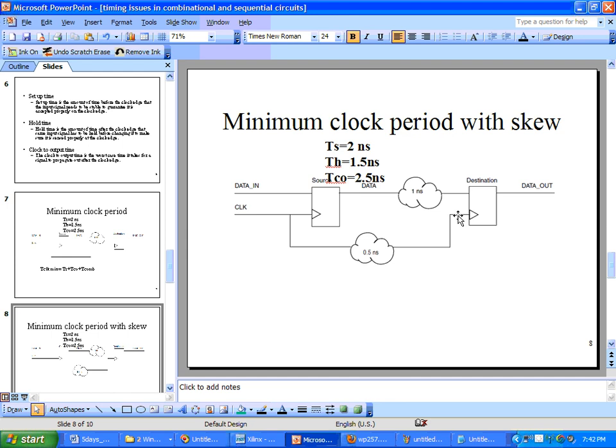So if 15.5 nanosecond has to come over here, then when can the clock edge come on this flip flop? Okay, let me again get into the picture. On 10 nanosecond the clock edge you gave here. Then next you have to give a clock edge on this one at 15.5 nanosecond. If it is 15.5 nanosecond here, when can you give it here? Another 0.5 nanosecond early. Got it? Means at 15 nanosecond itself you can give. Right? Now you see, because of the skew problem, your circuit is becoming faster. Isn't it? Now with the 5 nanosecond clock period only you are able to run.